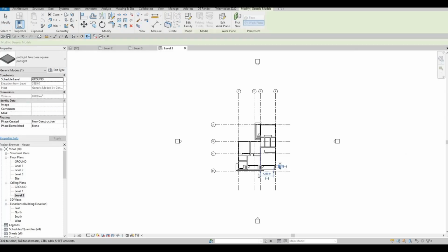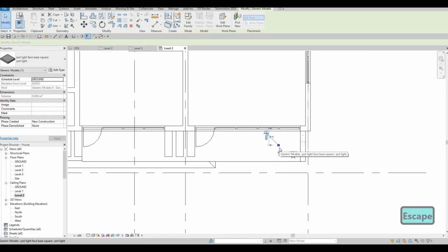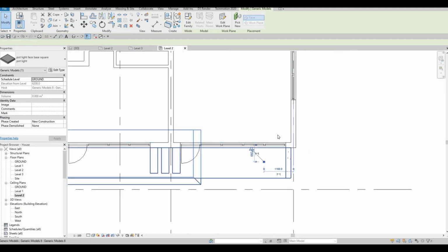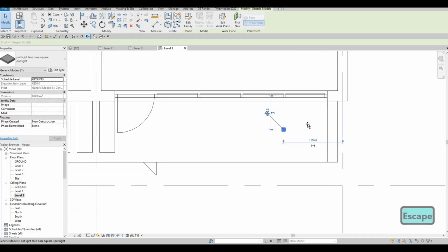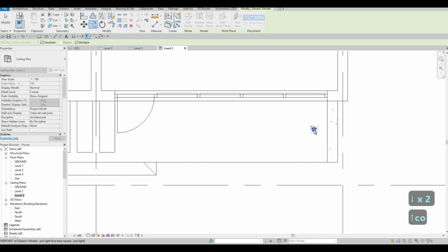Let's go on the ceiling plan, because we can see this one is the one for the ceiling here, so it's highlighted there. So here in the ceiling plan, I'll be able to see where I could put it. I'm just eyeballing it now. I'm going to add it in the center, and then I'm gonna put some right here, and we're gonna nudge it in place because I'm just gonna eyeball it.